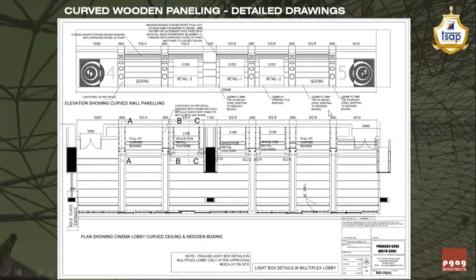Then he is not supposed to compromise anything in the width of the wooden boxes which are going to come. For example, I have specifically written the 600 mm dimension as a stagnant dimension. That dimension is going to be followed during execution of this paneling. Whatever he does, the adjustment is going to be divided into equal parts. Though I am seeing this dimension right now as 2.1, if I have written it as equal B, this dimension may be 2040 also as per site condition.